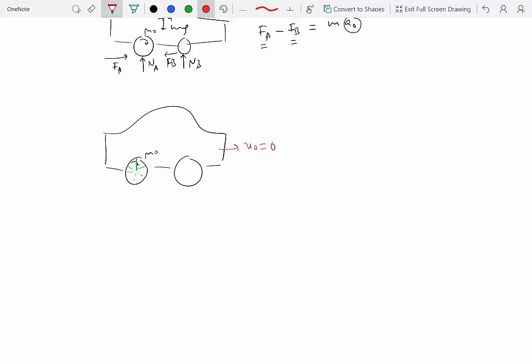Front wheels are unpowered. So the front wheels are actually not going to even move. There is no friction acting on the front wheel. So if you draw a free body diagram by itself, there is no friction. There is the normal reaction. This is NB, and there is the weight of the wheel, okay? So let's say that's simply W, and there is no other force on it. That's it. So N is balanced by the weight. There's no friction force to even make it rotate in this direction or that direction. So if you have a line in this wheel, it always remains vertical.